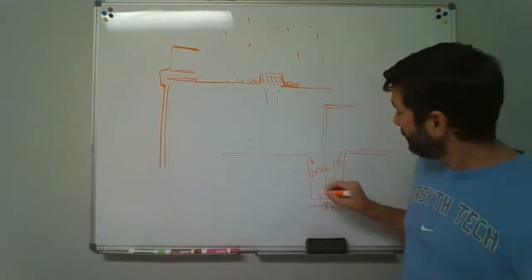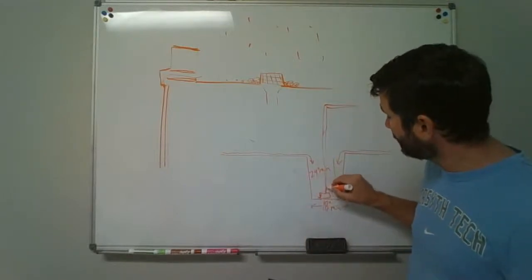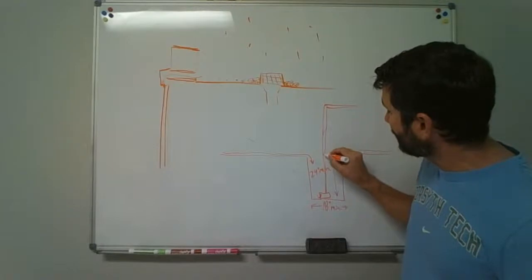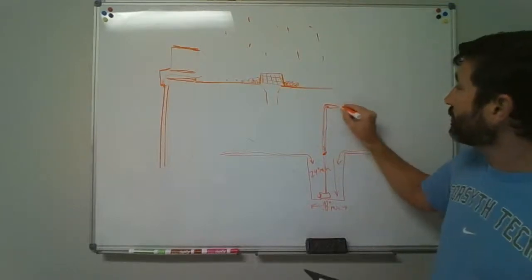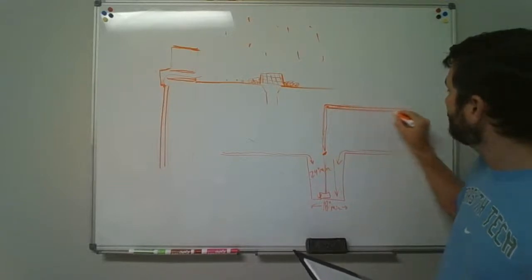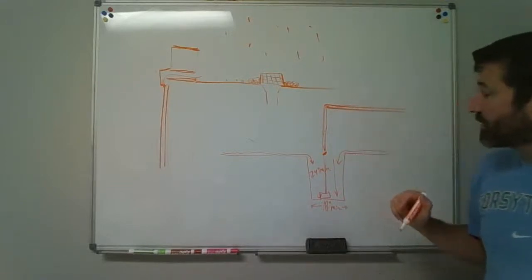Check valve. So when this thing pumps and the water flows in here and it kicks on, it pumps up, but you've got a check valve in the line that doesn't let anything drain back down through. Now, of course, when you get to this point, that should be pitched so that it flows by gravity.